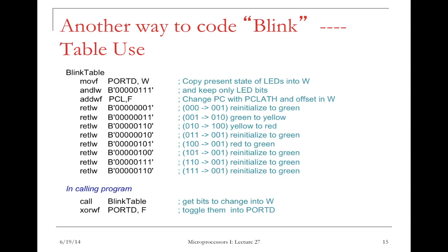With these two ones, you actually inverted this green light and yellow light, because they're doing exclusive OR. Everything you exclusive OR with one, you invert it. So what we're really doing here is, if you have a green light, then take the lower 2 bits and invert them. That's how we got this yellow light.